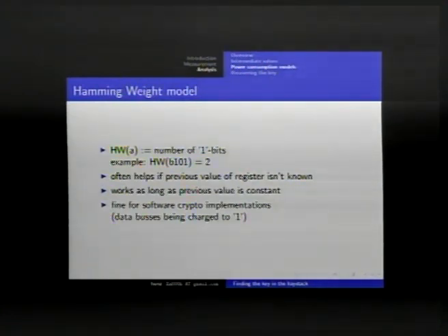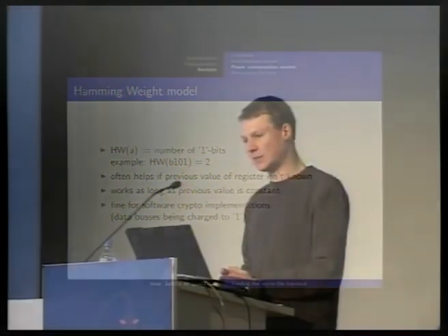This often helps if we don't know the previous value of a register, and it works as long as this previous value is constant. It is also fine for software crypto implementations because there are often large data buses within microcontrollers, and these data buses then need to get charged if they toggle to 1.